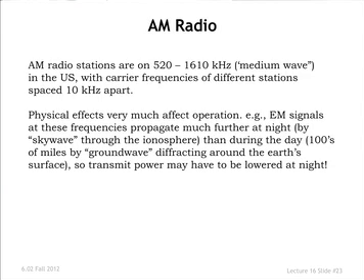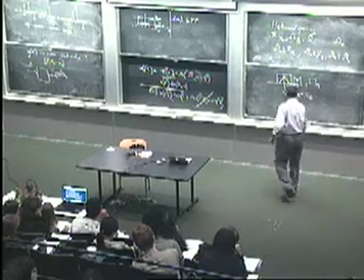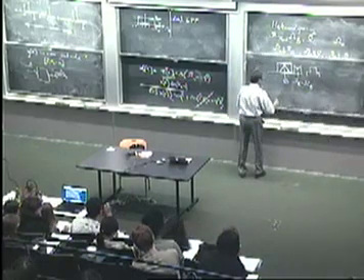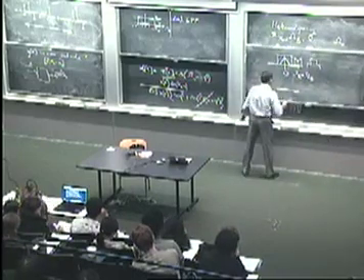The AM radio we see around us now is set up exactly to do the kind of thing we're talking about. You've got some frequency spectrum that the FCC allows you to use. Different stations are given different carrier frequencies to operate on, and they're instructed on what bandwidth they can occupy. The carriers are 10 kilohertz apart.